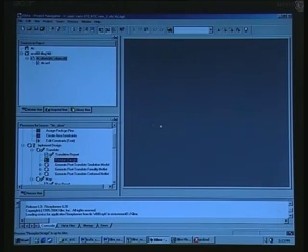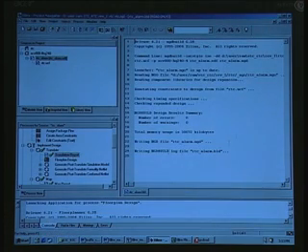These are all basically windows, and if I double click somewhere here you will get another window energized, and you see in total 4 types of window. This window is known as sources in project, and it is here where you will get the EDIF file and UCF file, and you will have to key in here, and then you can even change these files if you want to go for some other project.